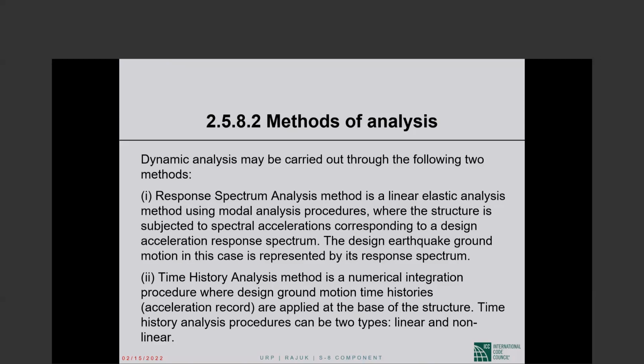Okay. Entire chapter 16 of ASCE 7 is devoted to nonlinear time history analysis. That is not our topic today. We will concentrate on modal response spectrum analysis, and when dynamic analysis is required, the vast majority of engineers would still do modal response spectrum analysis. And that's definitely true outside of the US. In the US, I think things are changing rather rapidly in favor of response history analysis.